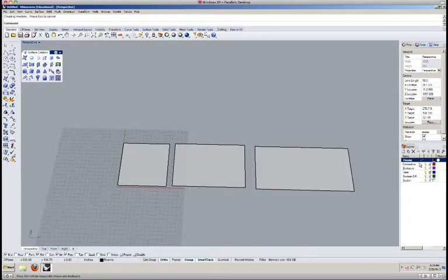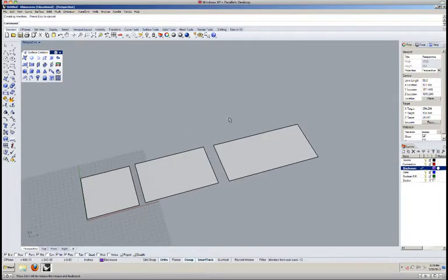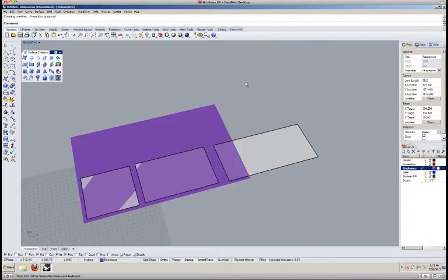And then I'm going to click to my enclosure layer, and I'm going to go ahead and draw that. And I'm just drawing the base dimensions at this point. We will go through how to extrude these up into volumes shortly. So I'm going to draw my base plane, and I'm going to draw it over top of these guys. The dimensions of that are 40 feet by 27 feet. And that should allow for you to encompass some of the different volumes.